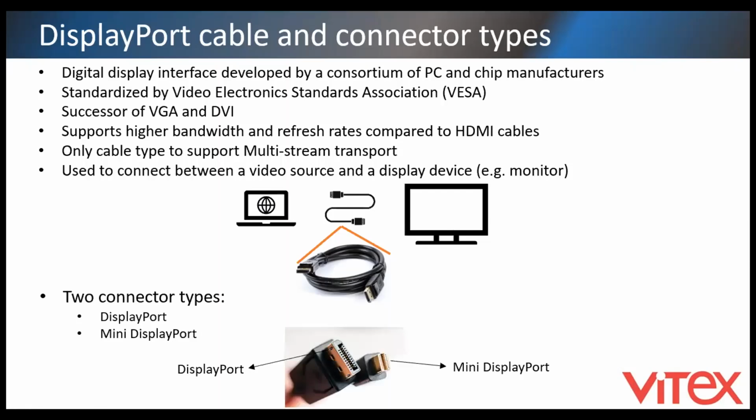So there are two types of connectors. One is called the DisplayPort and the other is called the Mini DisplayPort. Both of them are certified by VESA, and the Mini DisplayPort was specifically developed by Apple to be used for their laptops, which was later replaced by Thunderbolt. But that's for another discussion. So as you can see, DisplayPort is a wider adapter and the Mini DisplayPort is a shorter adapter. Both of them have 20 pins, which are used for different electrical connections.